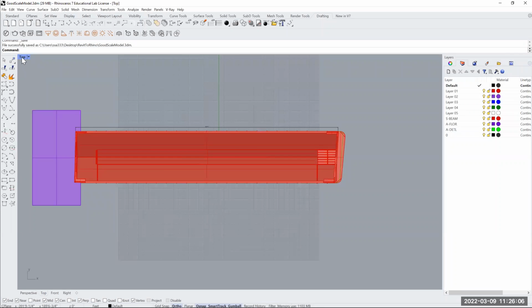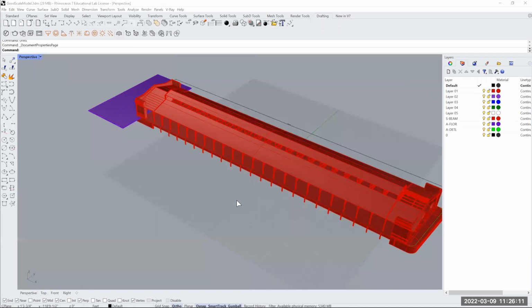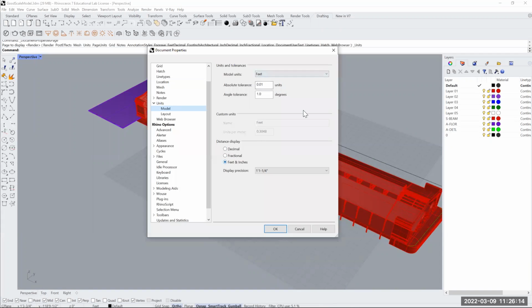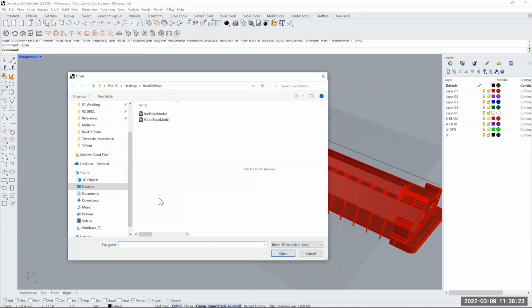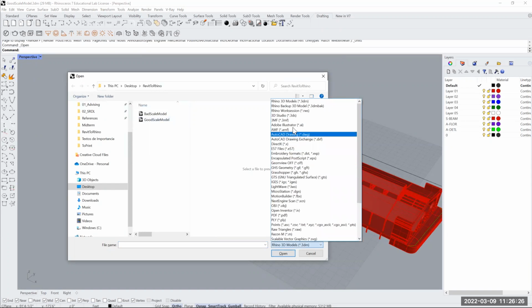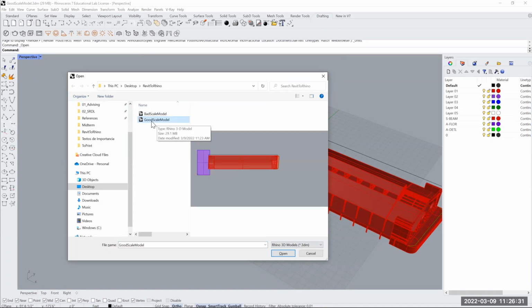So when I did that, basically I ended up with two different Rhino models. As you know, before importing, I set the units to feet and inches, and then you import the first model, the DWG model, and then in a different file the second one. So if I pick out everything I have, I actually have a good scale model. This comes from a DWG that was set correctly as foot, and then this is the bad scale model that was set to inches. So I have two of them.